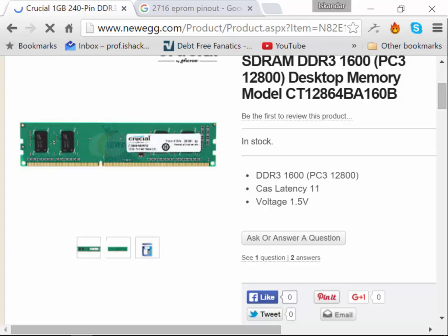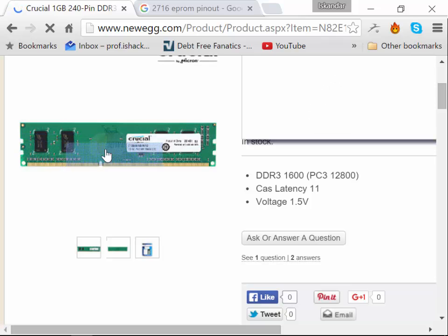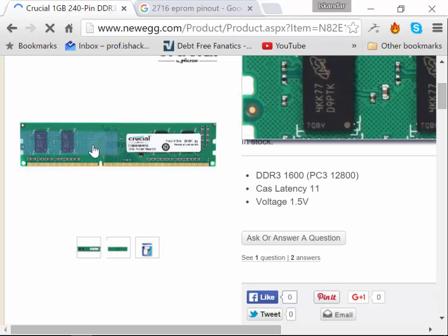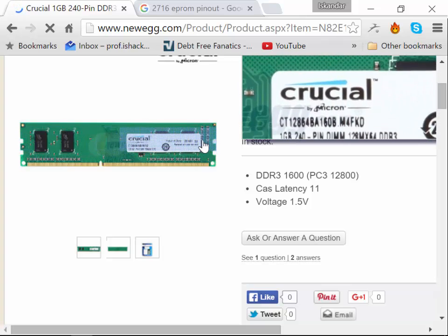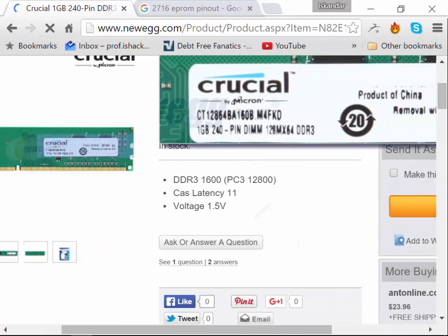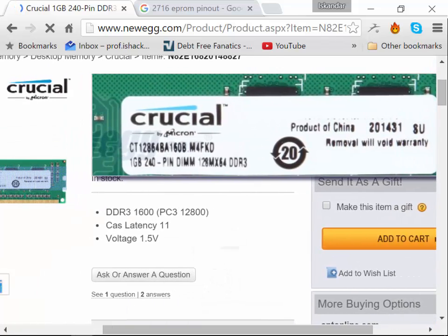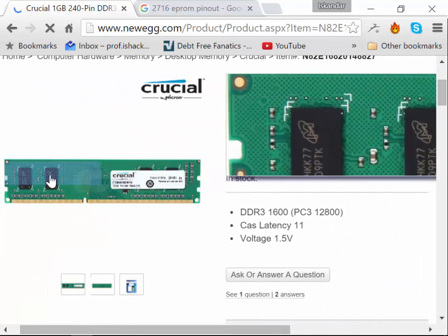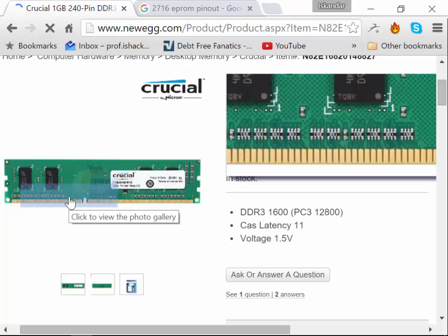This one has got 4 chips. One of the other issues is that with a large number of cells, you run out of pins. I'm not going to get into that. Anymore, we're talking 64 gigabits by 1. DRAM is almost always going to be in 1 bit or 2 bit increments. Static RAM is by 8, and ROMs are by 8.